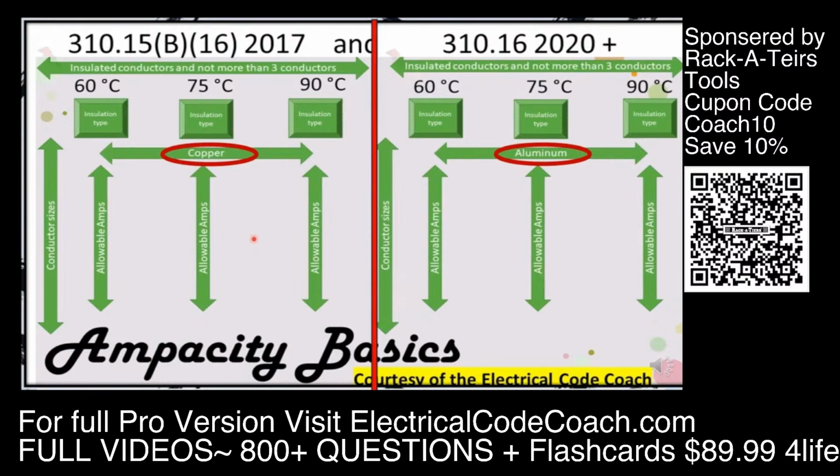So starting at the top, it gives us the scope of the table. We're not going to get into that right now. It comes later in the series. Then you'll notice there's a 60, 75, and 90 degree C columns. Below that are going to be the insulation types like THHN, THWN. On the left-hand side, you're going to have the conductor sizes, which is easy. And then in the middle, you'll find the allowable ampacity for each respective column.